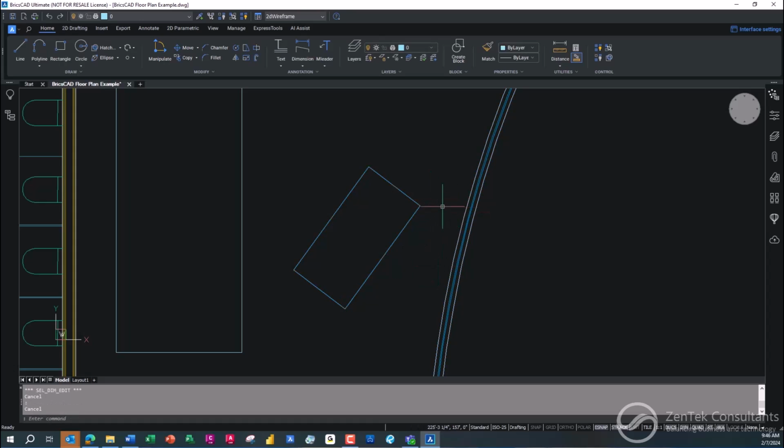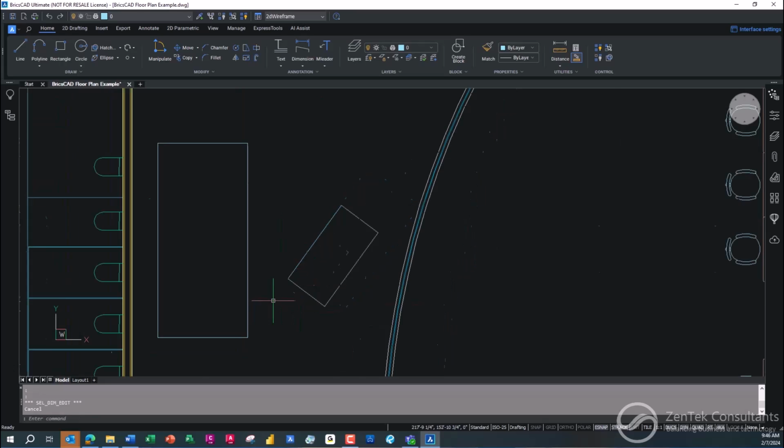All right, but it really is that easy. All right, and then I can go in and say, hey, now I moved that. What does that do to the clearance over here? So now I can go in and say that one's in the right spot. I don't want to move it, so I'll pick that first, and then I pick this one. All right, I've got 2 foot 3.25. All right, that should actually be 2 foot 6 for clearance, and we're good. Our equipment now lays out. It's clear. It'll set. We can get it in and work with it.